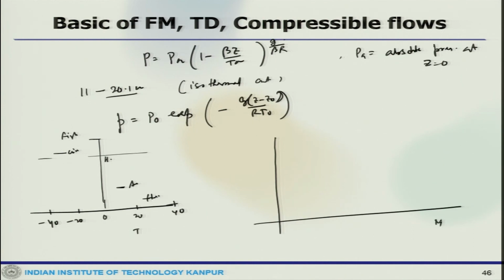This is Mach number, close to 0, where there is a curve, then 1, then 2, and this is 15, 30, 50, these are altitude in kilometers. So at low range again your helicopter, piston engine, turbopropeller, then you get turbofan, then military fighter, ramjet, then commercial jet works between 65 to 80, then you have other fighter jets. So this is another envelope which you will get.